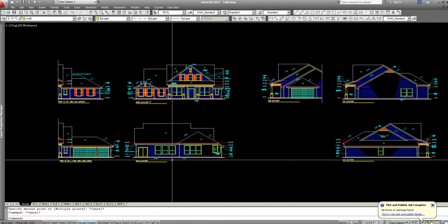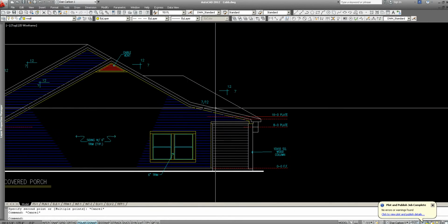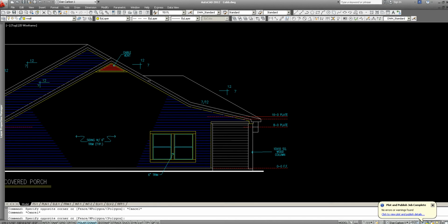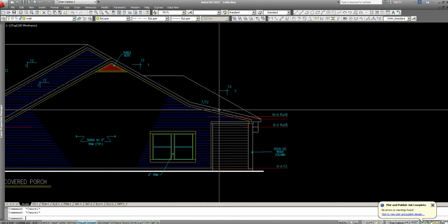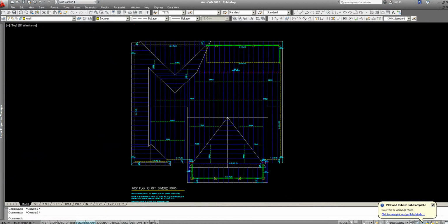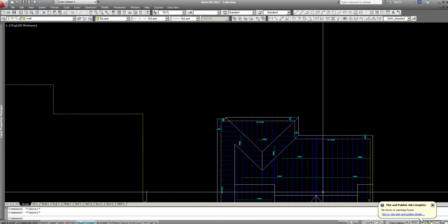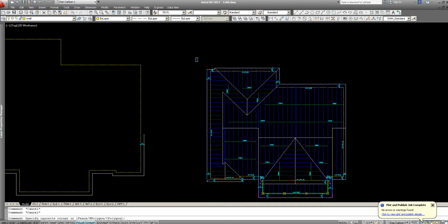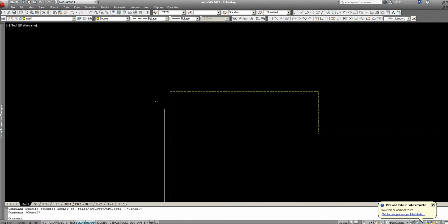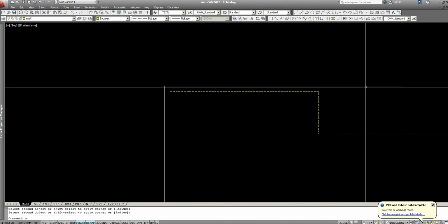Incidentally, it looks like we have a couple different ways of doing this roof. I'm not sure why we have this. We have a 7/12 here on this line, and that looks like about a 3 and 12. I'm not sure why that's there. I don't see that as being required, although I do see it on this plan. Here's that line of pitch break. Our plan does not have it. So we're going to go with the version that does not have it, see if we can make it work. So what that means is that everything here is just going to be 18-inch overhangs.